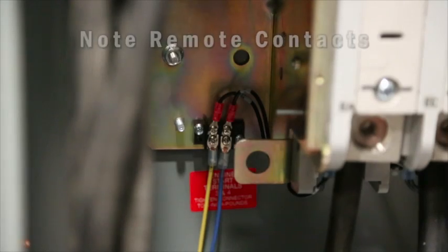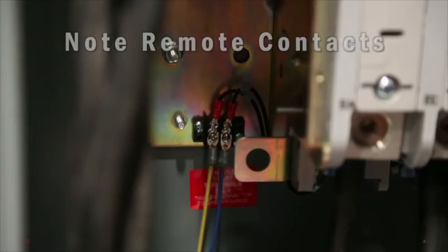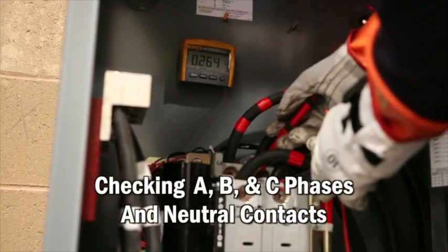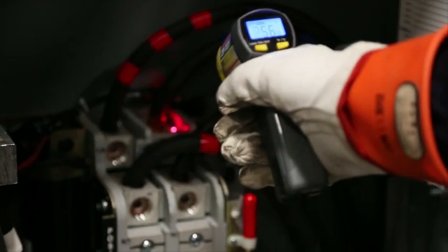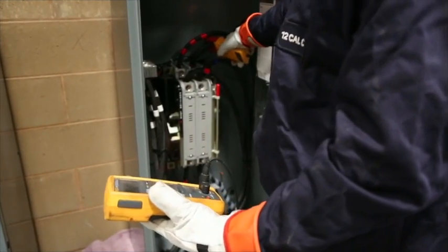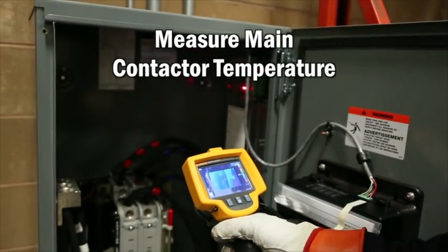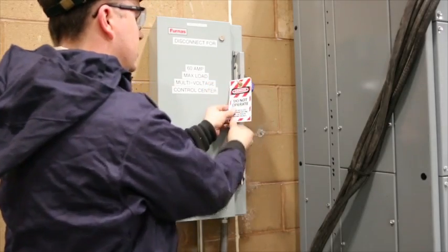Check the remote contact that provides the signal to the generator controls, indicating the status of the utility supply. Check for any voltage drop across the contacts that would indicate poor condition or a fault. Use an infrared thermometer to determine contact condition and whether a poor condition is resulting in too much heat. Record any voltage drop found when the generator is connected to the load. Note in the maintenance log the temperatures across contacts. Place a lockout tag on the power source.